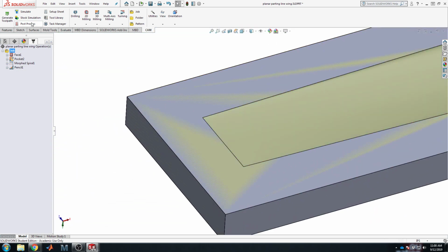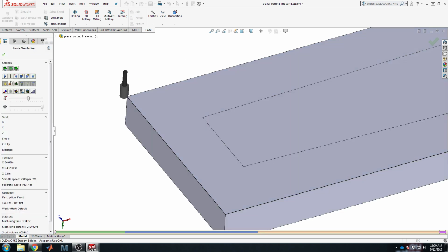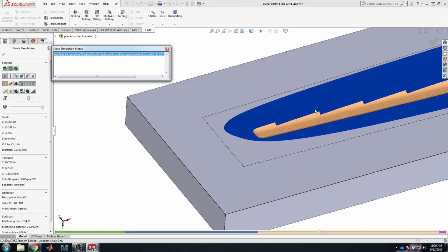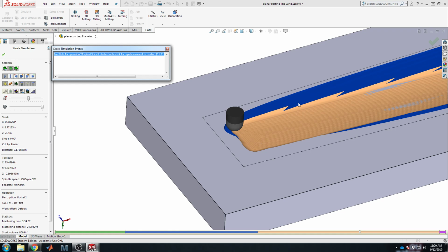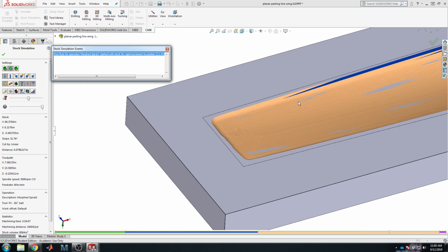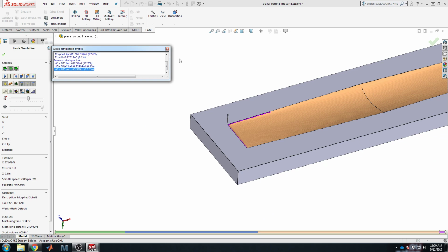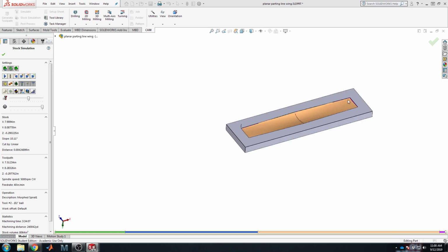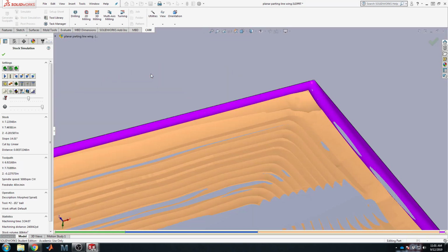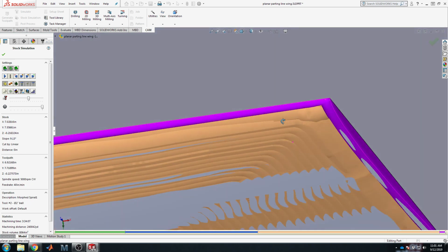So now if we look at the job and see what's left, by taking the time to do another tool change and another operation, you save hours of time on this surface finishing portion, and then lastly can sharpen up the edge cleanliness by using a 1/4 inch ball mill bit.